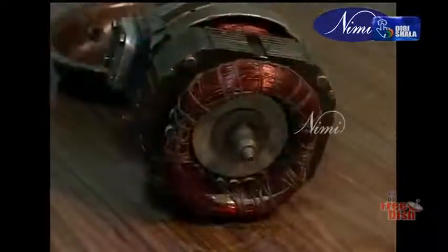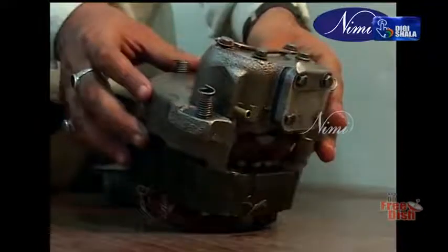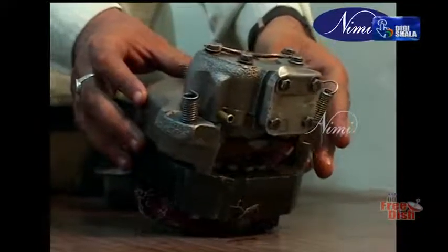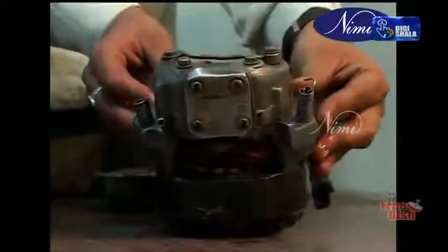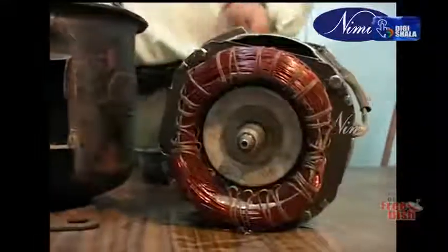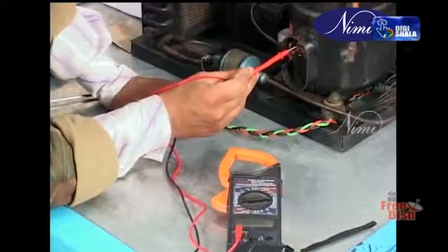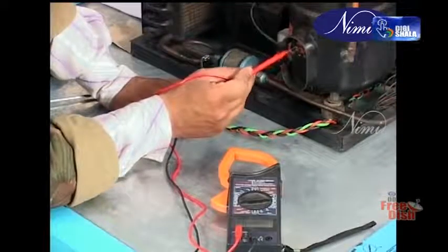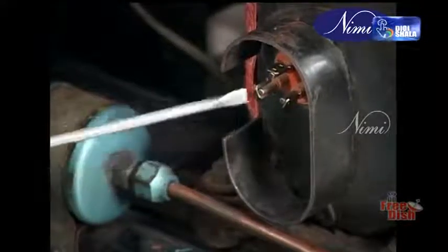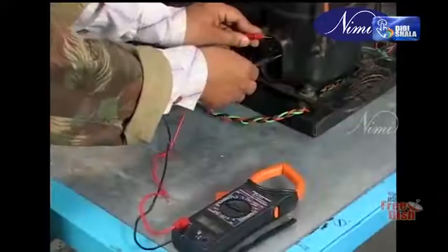A single-phase compressor has two motor windings, the start winding and the run winding. These two windings are wired together in series inside the compressor motor stator. Three wires are attached to these windings, one at each end and one at the common junction of the two windings. The pins are called the start, run and common terminal pins. The key fact you need to know is that the starting winding always has a higher resistance than the running winding.